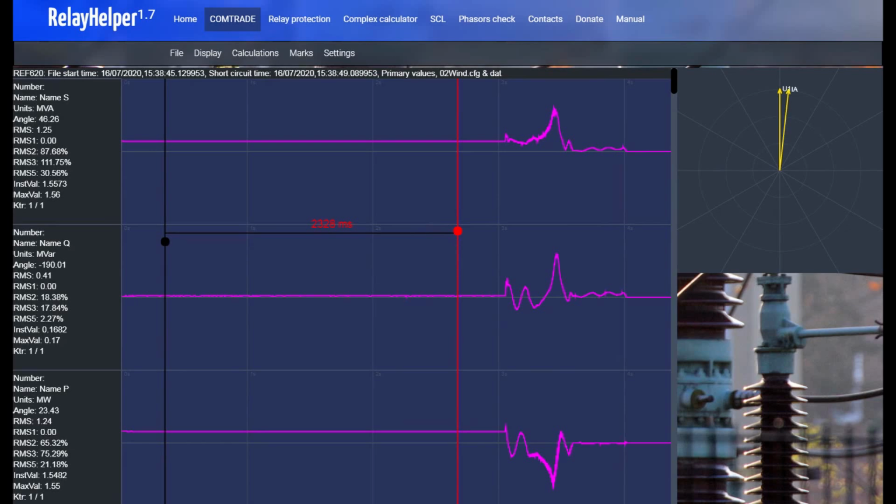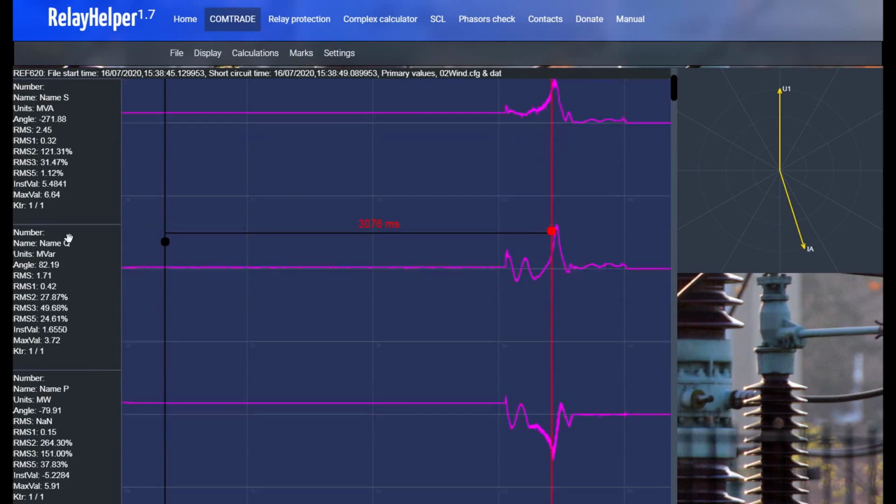In this case, the wind farm had only one connection to the grid. Another 110 kV line was disconnected from the grid before, and it happened that the primary protection communication channel was damaged, and we saw backup protection relaying.